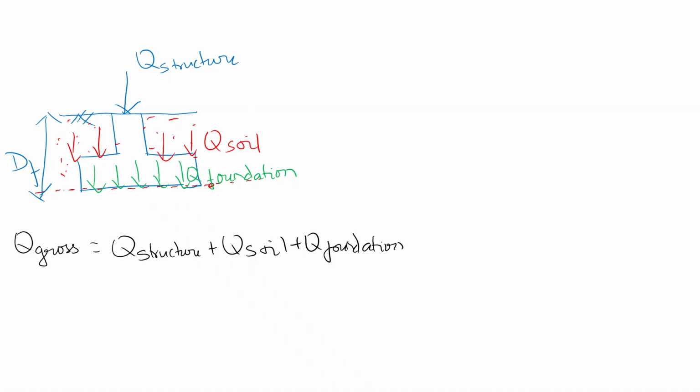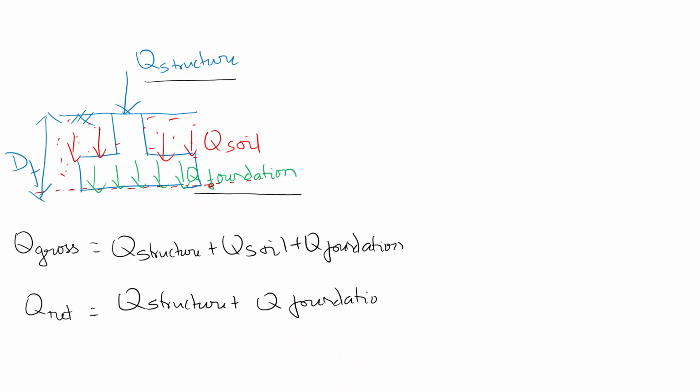right? But think once, is the soil new to this place? The soil has already been present. Only the new things here are the load from the structure and the load from the foundation, because that is what we have constructed, right? So the net load is nothing but the load from the structure and the load from the foundation. I believe now you can understand the difference between the gross load and the net load.